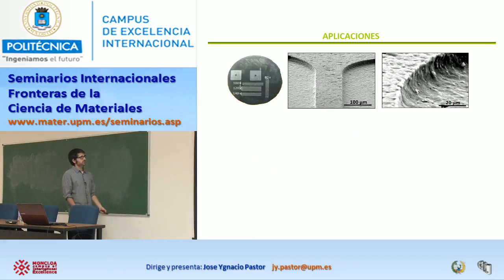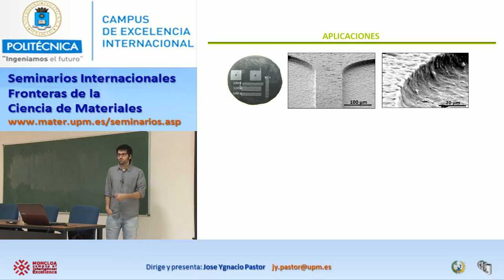Okay. Then we take our material, the classical disc from the SPS, and you should optimize the voltage that you apply in your EDM, but it can be processed easily. Silicon nitride, that is quite hard to machine in several hours and so on, in seconds you can perform these kinds of things. And also, as you see, the accuracy and the roughness are quite good. I mean, the cuts are perfect. It is 100 microns, and even if you go in detail, here the roughness is quite good.